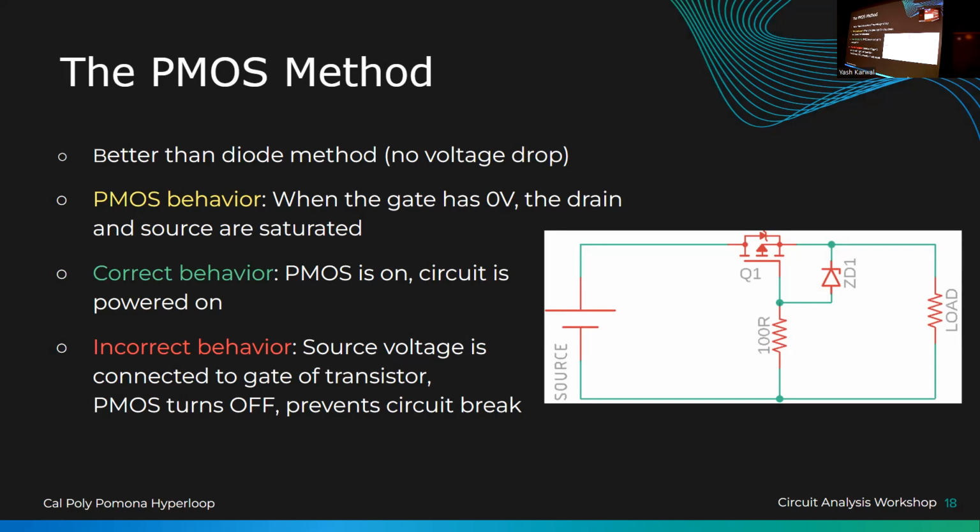And that's called cutoff mode, right? That's when the two terminals don't short at each other. Now, there's a whole lot of other complicated things you can get into regarding transistors. That's the simple way to think about it. If you're using an NMOS, which is like the opposite variant of the PMOS, then it's opposite, right? 5 volts turns it on, 0 volts turns it off.